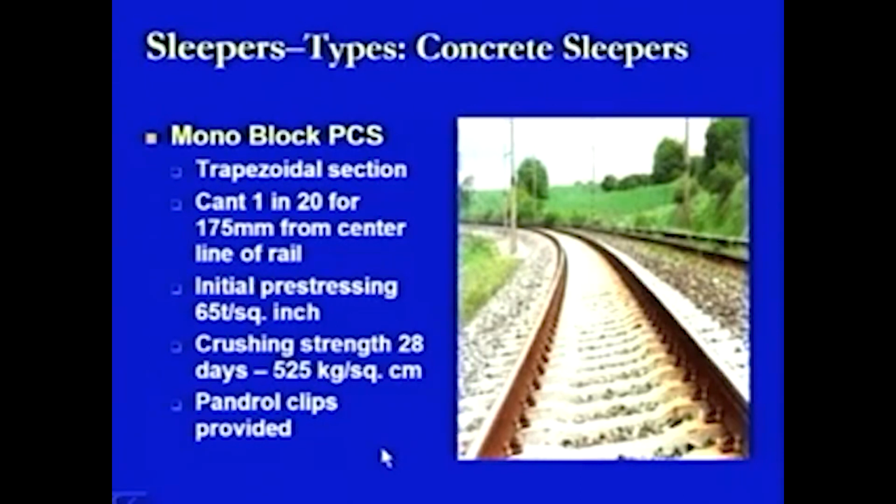And pandrol clips are provided so as to join the rail section with the concrete sleeper. So, at all these locations whatever we are seeing are the fixtures, the fastenings which have been used to join this rail section with the concrete sleeper, and generally this fastening is the pandrol clip which is being used.